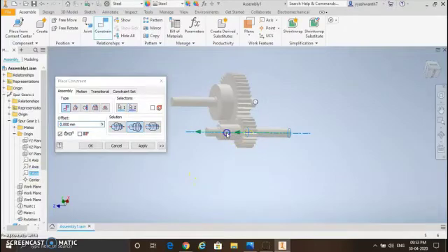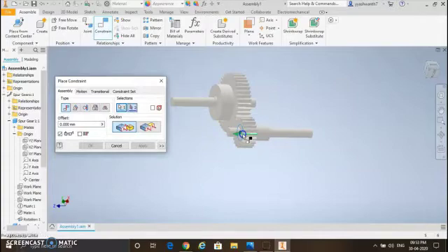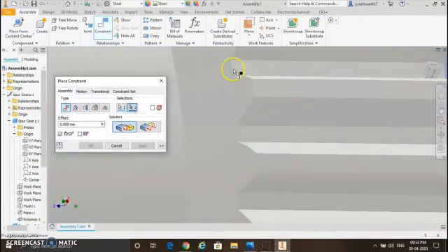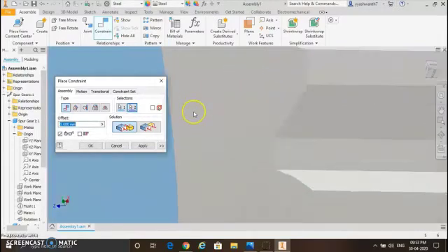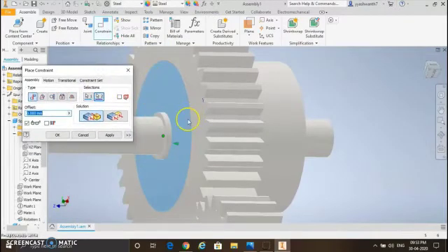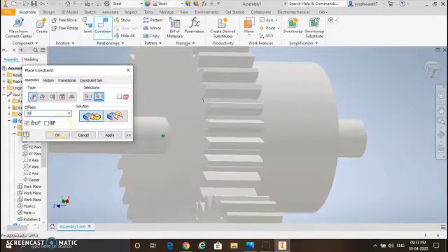As the axis is fixed for both the gears, they are moving along the axis, but they are not fixed to the gears. For it, we must constrain them. Before constraining, let's make the gear shaft fixed at a middle position of the gears.